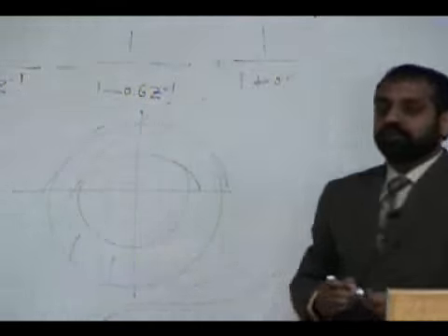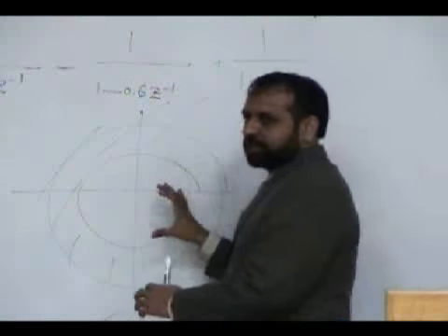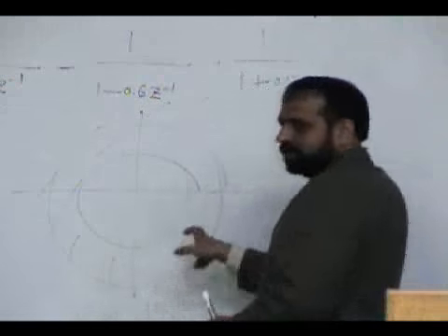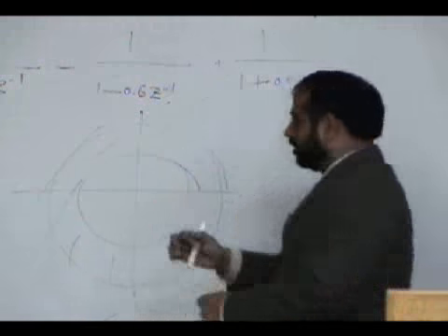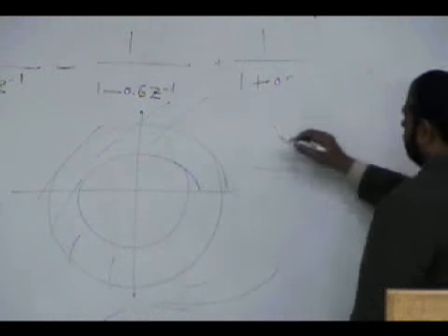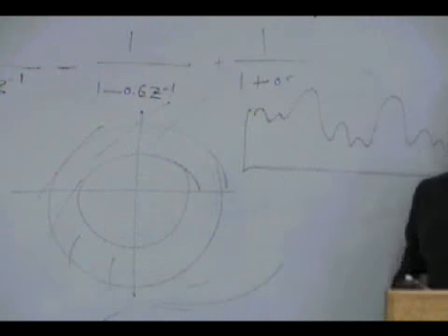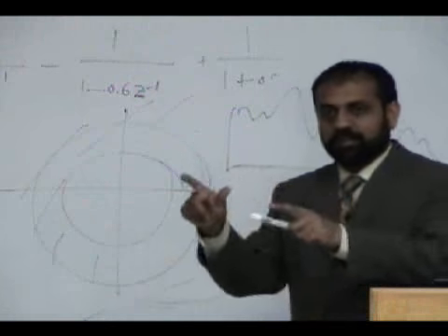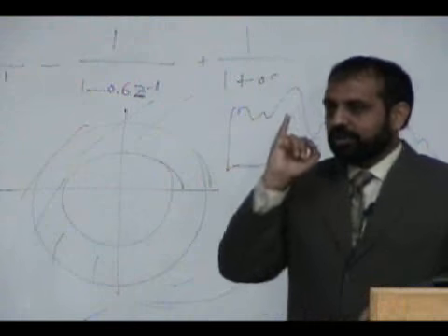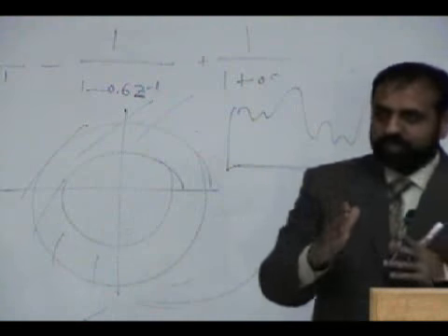And the Z transform on the unit circle is the Fourier transform. So what you do is you put a ring of unit circle and take the surface out, a cross section of this. That is the Fourier transform. Okay? And you lay it down straight, and what you see is the Fourier transform. This is the cross section of a Z transform at r is equal to 1. The Fourier transform is the Z transform at r is equal to 1, and this is the only Z transform which we are interested to compute. Put r is equal to 1, compute.